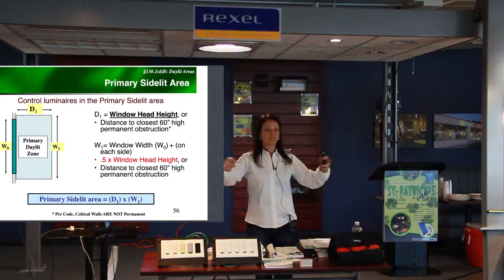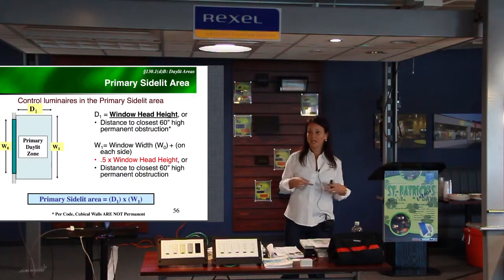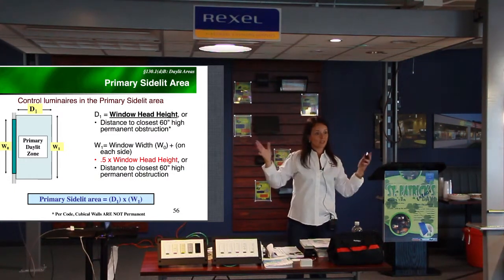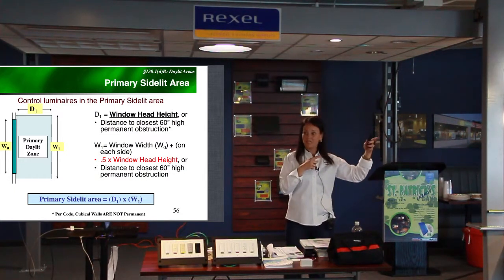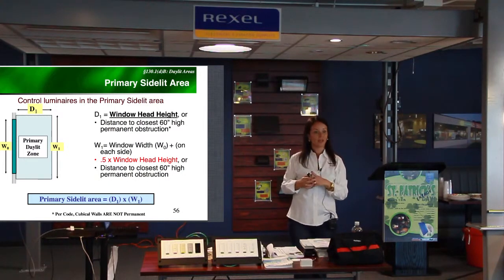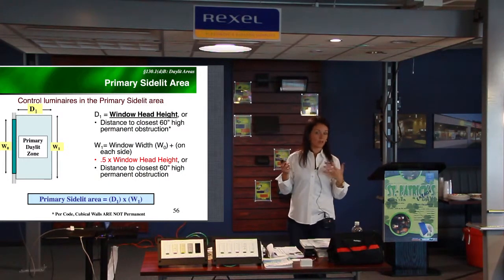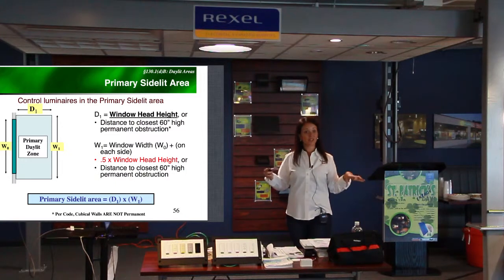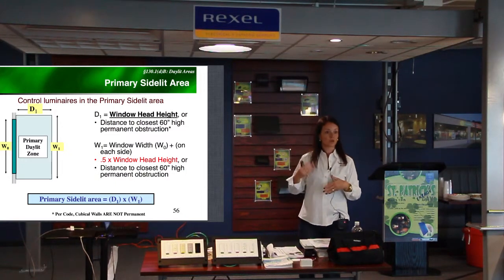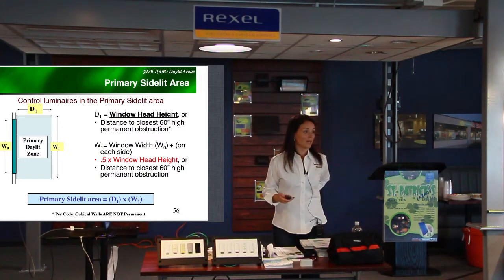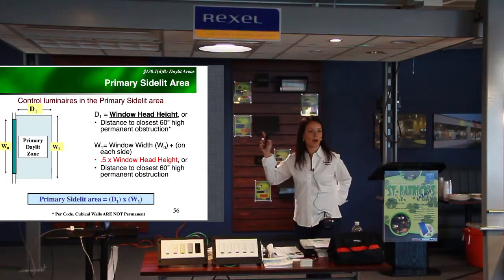And the issue with making a larger area for the daylighting zone is every fixture that is inside of that, or even partially inside of that area, needs to have a daylighting control. So that's very important. Daylighting areas are getting bigger. So California is trying to use more and more automatic daylighting controls. That's what we can take out of this.